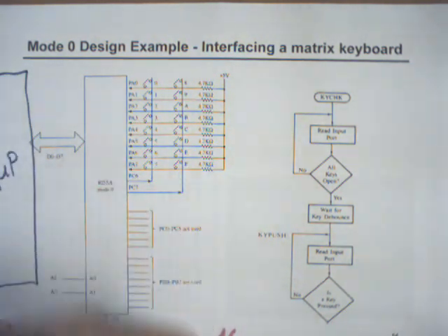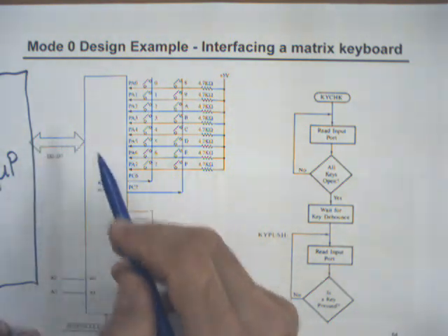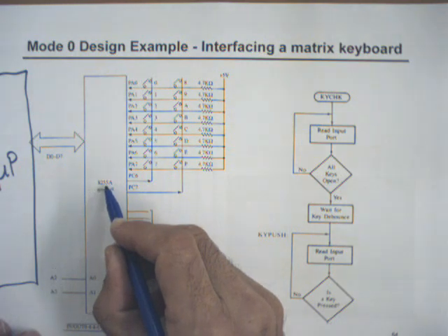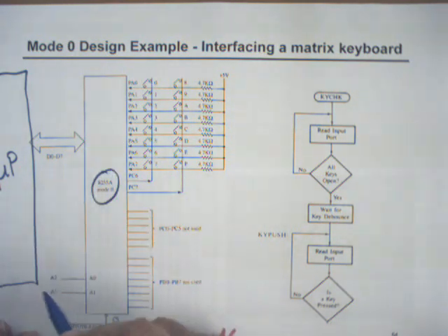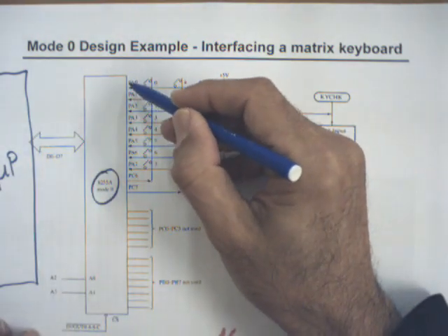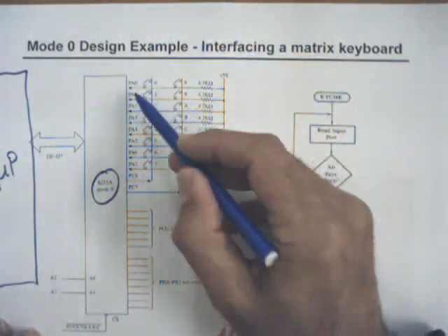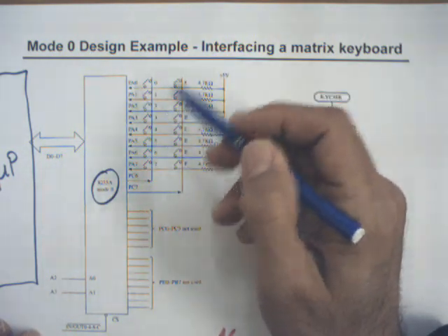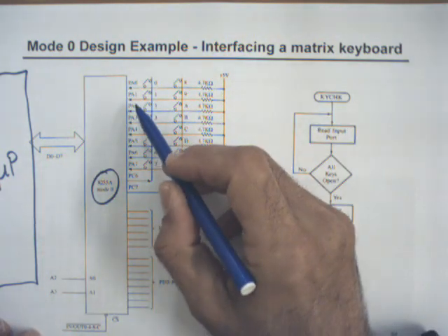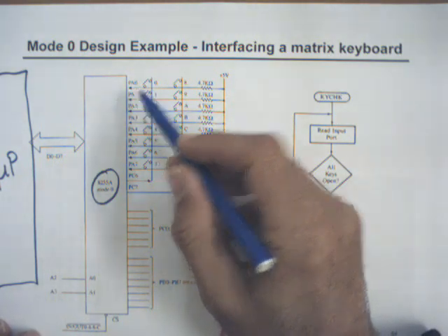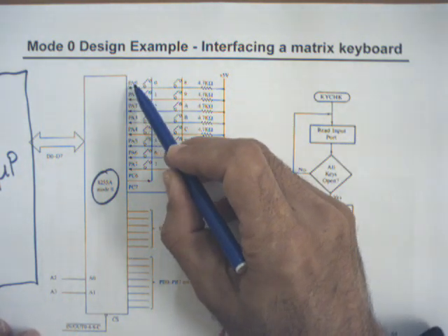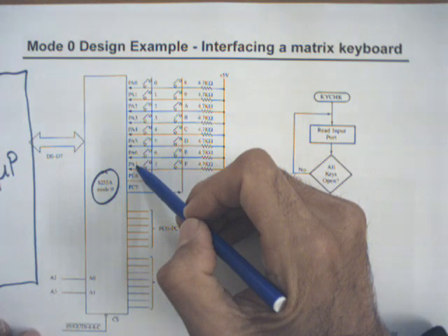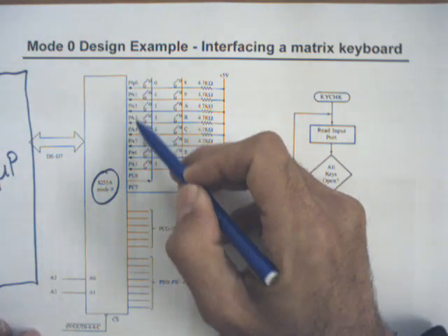There's a microprocessor over here, 8088 or 8086, and it's connected to 8255 programmable input-output integrated circuit. You may have 3 ports, where all bits can be programmed as input or output. So this is the final topic of your lecture. So PA0 to PA7 are port A0 to 7.